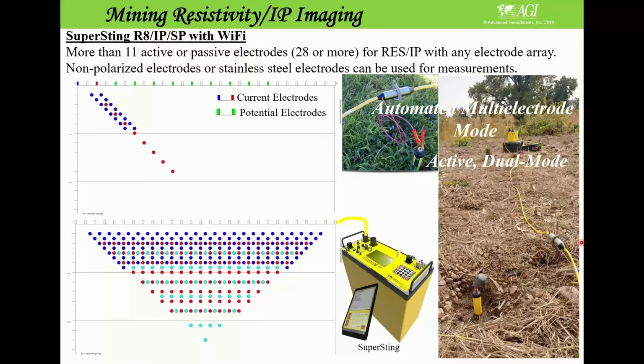Here's a typical field survey area connected to non-polarized electrodes. Here are the current locations. If this electrode is used for current injection, it just injects current. If it's used for measurement, the measurement comes just from this electrode. So this is a much cleaner signal compared to passive systems,